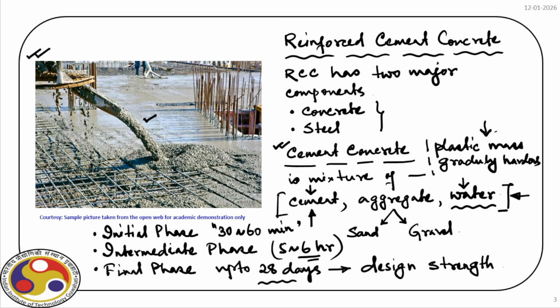Now here you should note that beyond 28 days also concrete gains strength, but that is a very slow process and we normally do not rely on that additional strength beyond 28 days. So in our design, we'll use the strength that the concrete achieves at the end of 28 days with proper curing. Okay, so now why cement concrete in particular is used in building constructions?